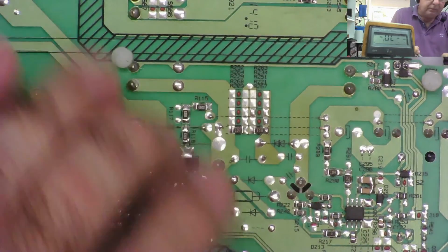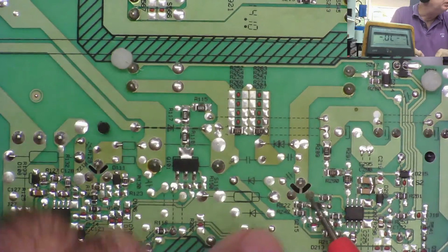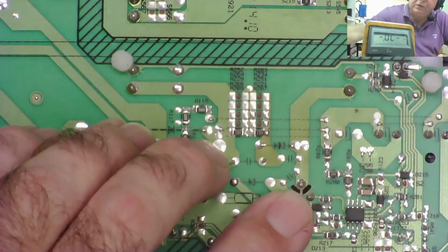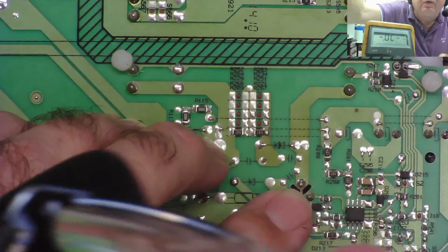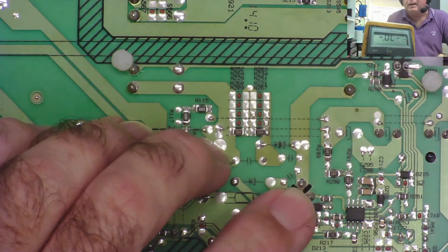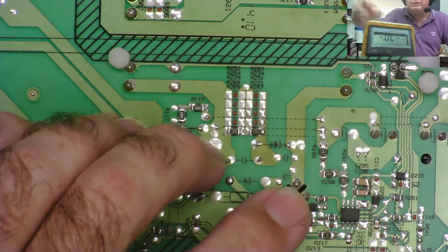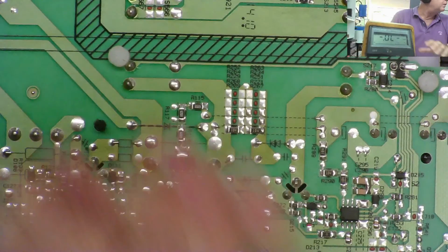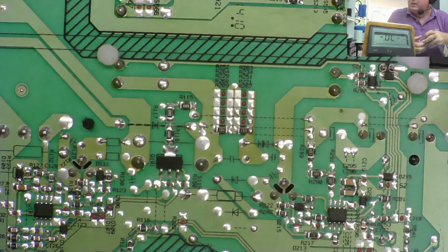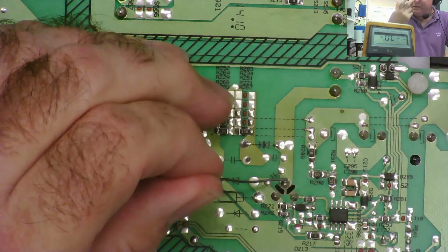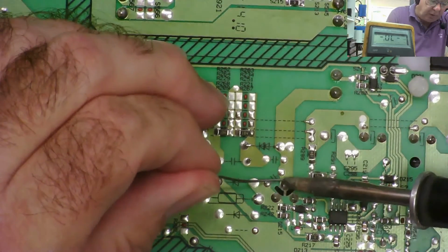If you have a transistor like this type and it doesn't quite seem to read properly in circuit, a useful little trick: we put the soldering iron on, get a bit of flux and a bit of leaded solder, and a bit of solder braid. Solder's around here somewhere. We use the thin stuff. I can't see it, I found the thick stuff. Another little trick we can do is this. If we're suspecting this transistor, and maybe we can see a diode reading where it's not the transistor, we can actually often check these in circuit.